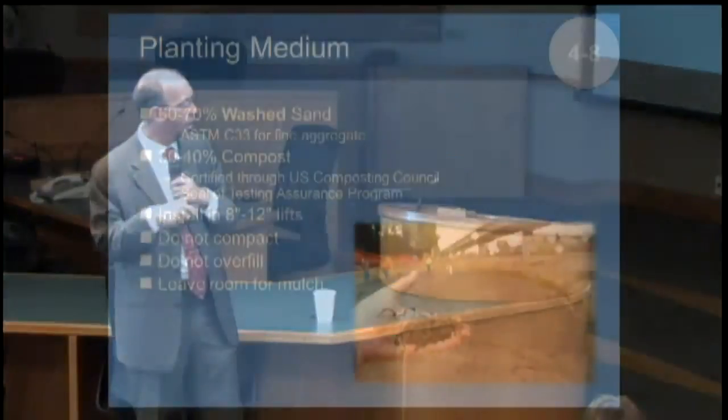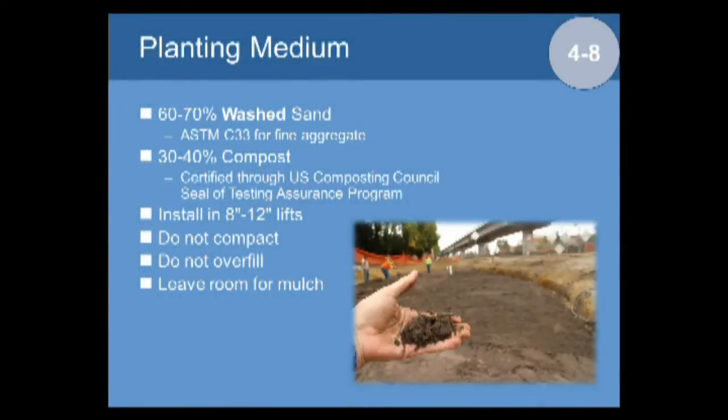And so folks will always say, oh, well, can't we put a little topsoil on top of this, or can't we add this, or can't we add that? The key thing is that as soon as you start putting any clays in there, you're taking the risk that it will fail. Often, when you get into a discussion with a contractor or an owner on this, and they say they want to do that, you say, well, the problem with that is that if it fails, it's going to be your cost to go and tear all those plants out, excavate all that material, haul it off-site, haul in new stuff, reinstall your plants. If you want to take that risk, that's going to be on you to set it right, because it's, of course, the city's responsibility to ensure that it continues to perform.